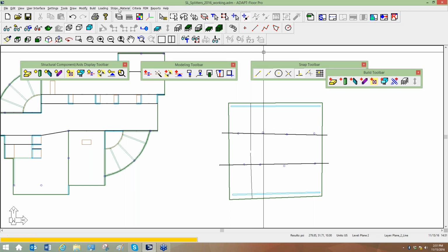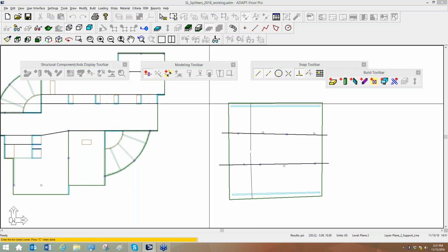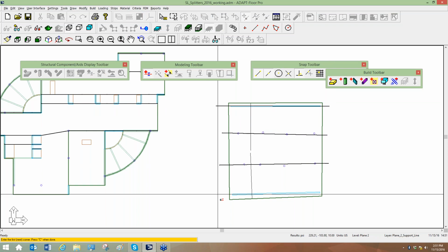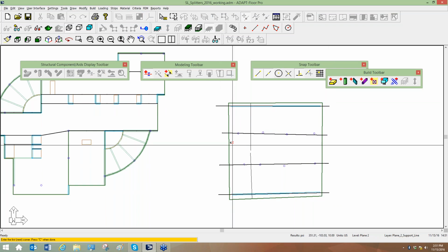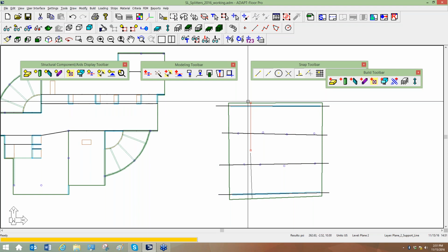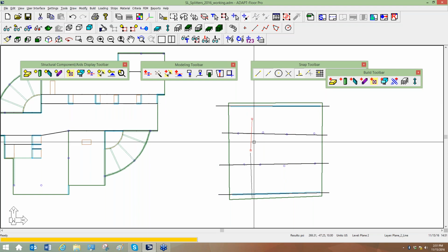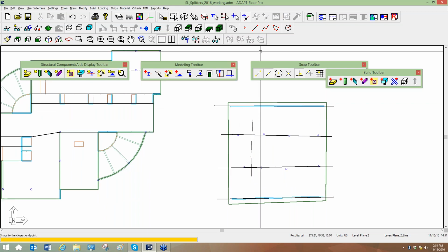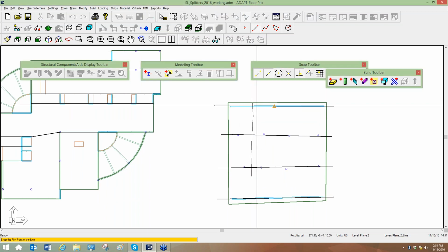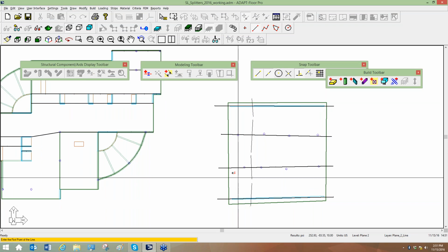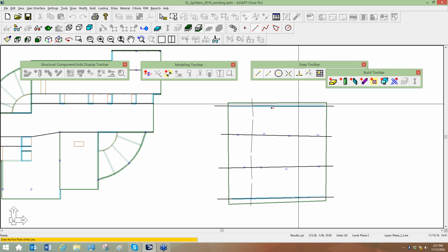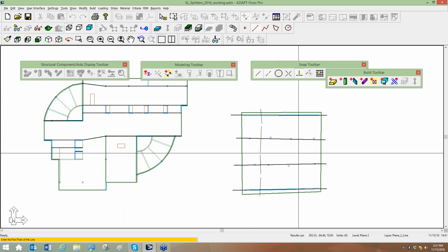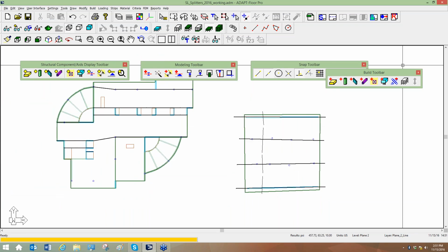So here we would definitely want to go and add support lines over walls. This just simply refines the distribution of tributaries, and now this section cut gets taken down to something like that. This gets taken down to something like so, and then we get 2 additional design cuts. There's obviously design cuts all along this strip. So this just refines the results for this particular layout and arrangement.